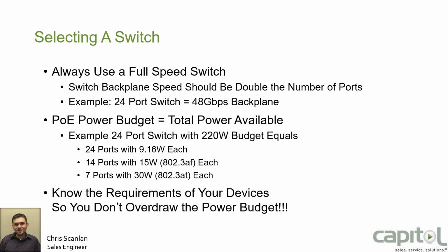So know the requirements of your devices. Any PoE device should have the power rating on it, how many watts it's going to take, as well as the switch will have the power ratings on it. If it doesn't, you may want to run for the hills. If you see a PoE switch that doesn't have a power rating on it, you may not want to use it. You may want to look elsewhere. So really make sure that you know the requirements of your devices so you don't overdraw the power budget. We all know what happens when we suck more power than the power supply is able to do. It burns out devices.